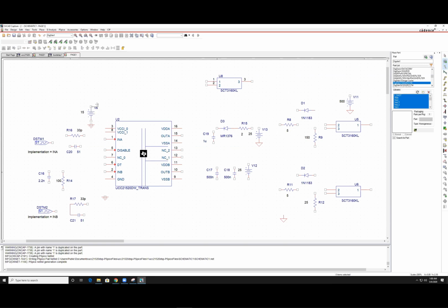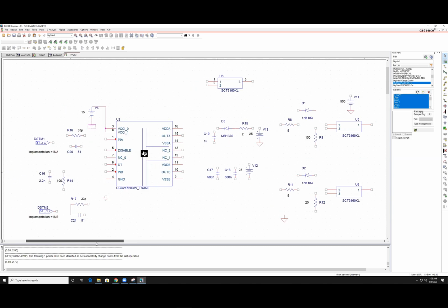So we're going to connect this to power the gate driver, to both pin 3 and 8. And we want to connect this ground here. We have a 15-volt input here. We want to keep this ground only on the digital side here. This is just to make sure symbolically we understand that this ground on the circuit side is different from this ground on the digital side here.